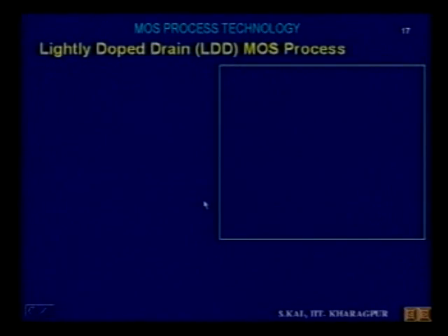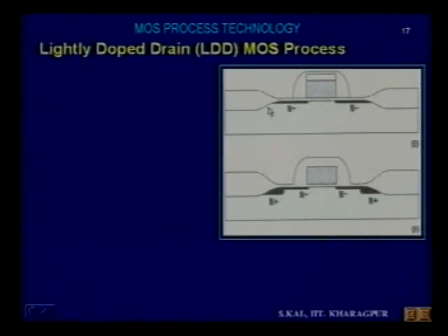In the next step, after thermal oxidation, when the polysilicon is oxidized, what is to be done? The etching of the oxide. And that etching has to be RIE, reactive ion etching, so that it selectively etches the oxide which is formed from polysilicon.